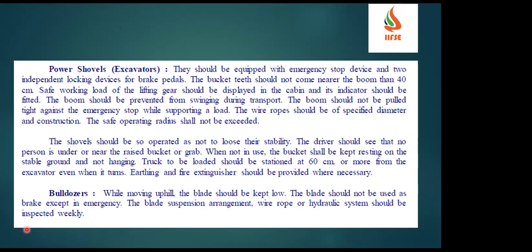Okay, these are the excavators, and the shovel should be operated so as not to lose stability. The driver should see that no person is under or near the raised bucket or grab. When not in use, the bucket should be kept resting on stable ground and not hanging. A truck to be loaded should be stationed at least 60 centimeters or more from the excavator when it turns. Earthing and a fire extinguisher should be provided whenever necessary.